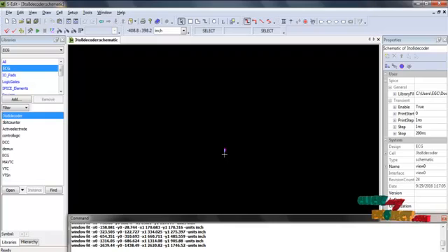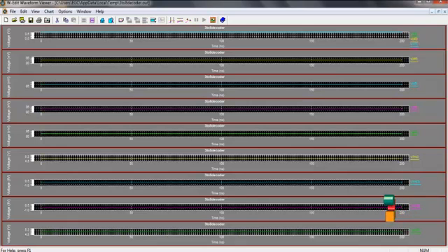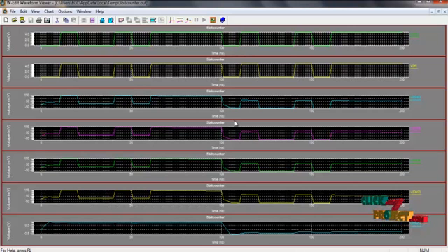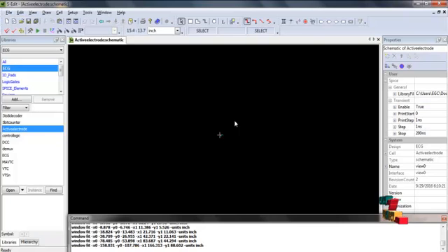3 to 8 decoder is the part of the 5 to 32 bit decoder block. Next we are going to see the waveform. This is the waveform of the 3 to 8 decoder. Next we are going to see the design for the 5-bit counter. The 5-bit counter consists of the JK flip-flops and the AND OR gates. Next we are going to see the waveform. This is the waveform of the 5-bit counter.